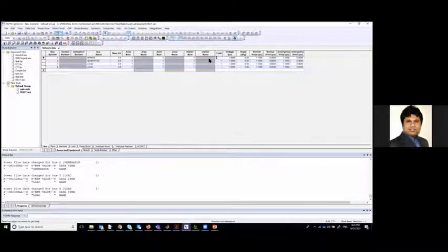For the infinite bus, we use 3, and for the generator bus, we use 2. Okay, these are the codes that we need. So that means if you look here, power flow data changes for bus 1, that means the infinite bus. Bus 2 is the generator bus. So this has been defined. All remaining buses are load buses now.